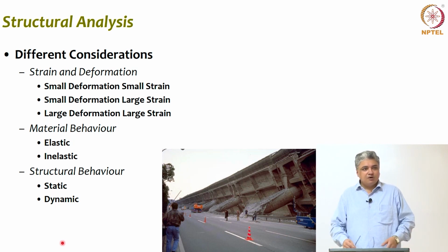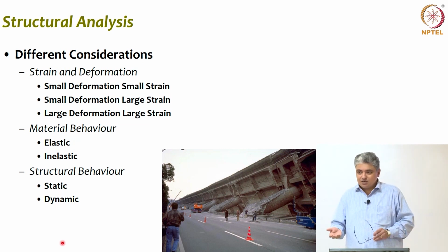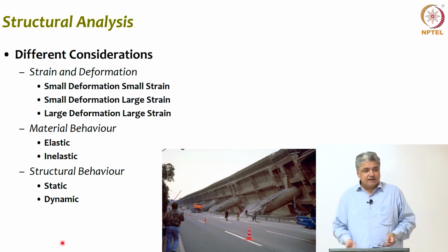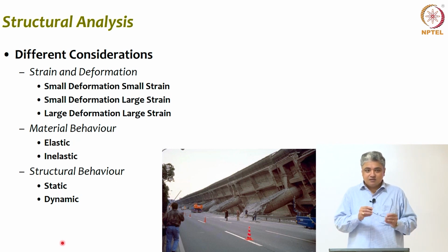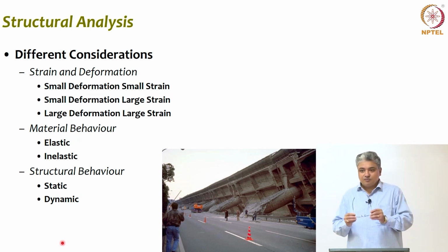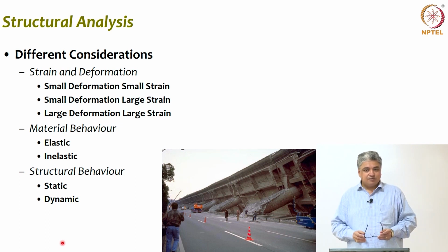But sometimes you have loads which vary with time, and that induces additional response in the structure which is time dependent, right? Those kinds of situations are known as dynamic situations. For instance, you have a very slender chimney and you have wind blowing past it. You will suddenly see that the chimney is swaying a little bit, back and forth, back and forth. That is a kind of dynamic response. Similarly, you will see a lot of videos about buildings shaking during earthquakes, right? That's another example of dynamic behavior.